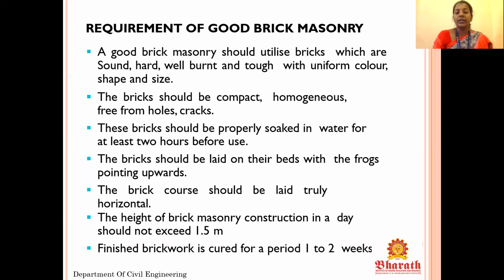If the brick is not cured properly, you can see the cracks easily. So the brickwork should be cured for a period of 1 to 2 weeks, minimum of 1 week and the maximum of 2 weeks. So these are the few requirements.